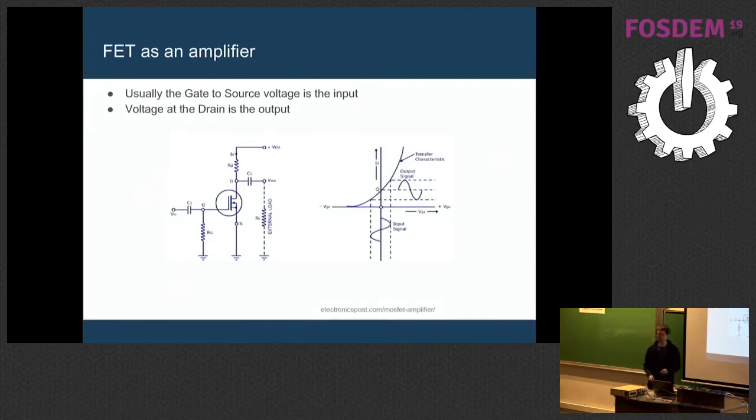This tends to be a pretty typical simplified circuit. As soon as you start designing these, you realize there's about 80 components on either side of these, and they never work the way you want them to. But we can see here, again, the circuit from the previous slide: the transistor, and the drain has a capacitor that's decoupling it from the power supply rail, and we're getting a voltage at the output. And so that's the signal outwards. Basically, we have the input signal, we're changing the gate source voltage, and that's producing a change in current at the output. And as long as the slope is greater than 1 across your resistor, you get an amplification.